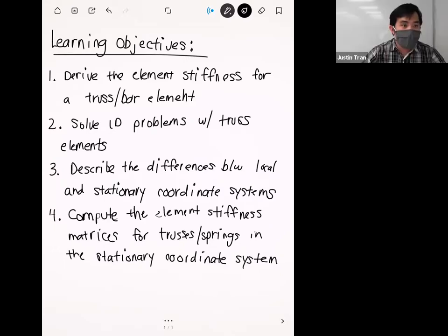So you can supply a moment boundary condition itself. One of the boundary conditions you can actually supply, we haven't used it in an activity yet, is that instead of a force boundary condition or a pressure boundary condition, you can supply a straight up moment. Then for the moment you would specify the axis of rotation for the direction. Okay. All right. Thank you.